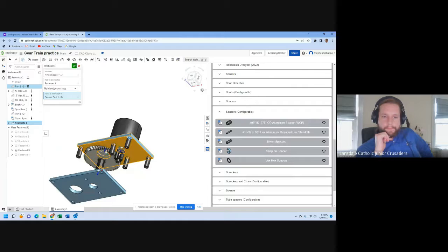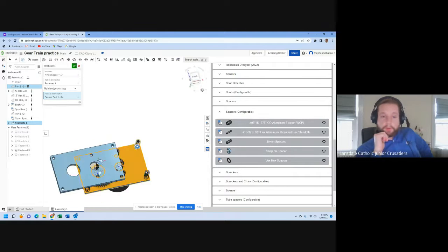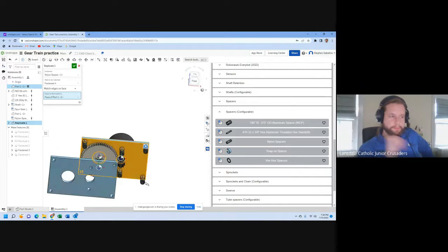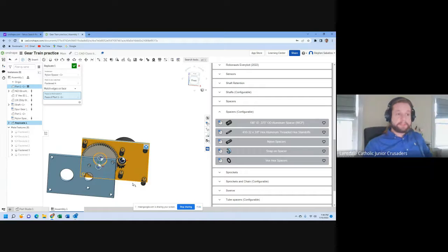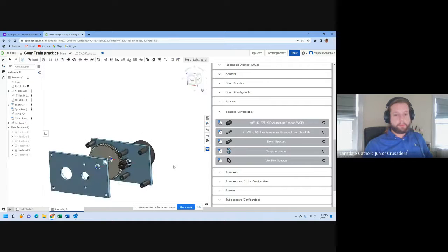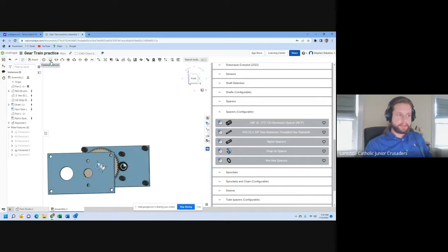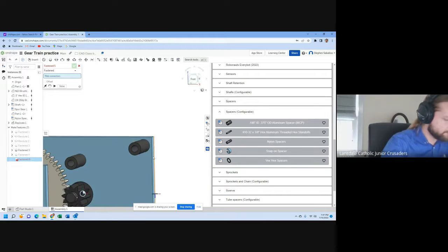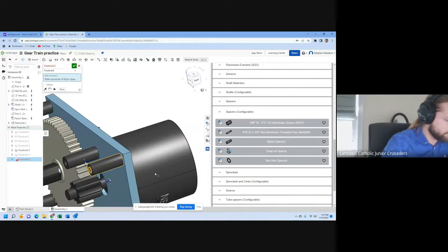Although I didn't necessarily need them there. That was just for the motor, right? Or maybe you don't need the ones on the outside. Oh, yeah, I guess I could have just... You can bolt long bolts right through into the motor, and that could be how your gearbox is built. Okay. Yeah, save on plate space. Save on plate space, save on bolts, save on spacers. And it makes your motor more easily able to be removed, right? Because now your bolt's on the outside of a set of plates and not on the inside. It's a little trick. A lot of teams do that. Sometimes it's more helpful in some places than others, but it's generally good practice.